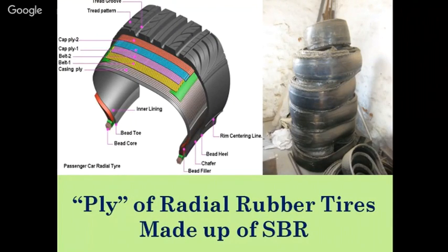But one thing I told you, that a building should have the initial stiffness to resist small earthquake loading. Now, if you see the base part of the rubber tire, it is a very flexible kind of material. It does not have any initial stiffness. If I use it as it is, how will I use it in buildings? It will fail. It will not serve any purpose. So the first problem is that we need to provide initial stiffness to the material.